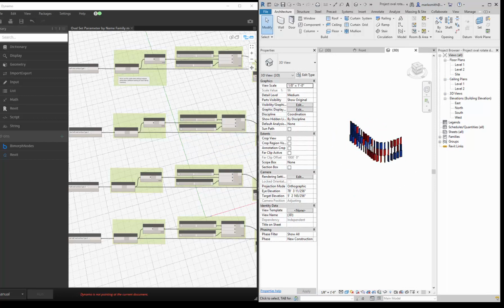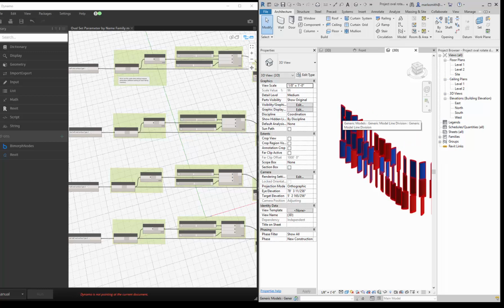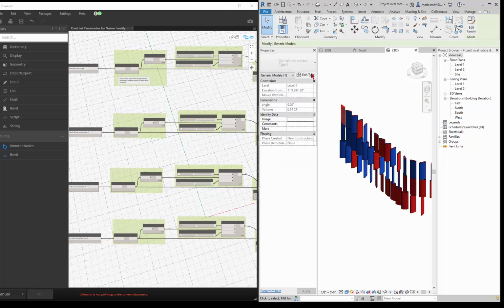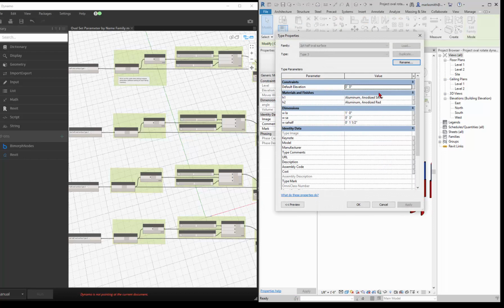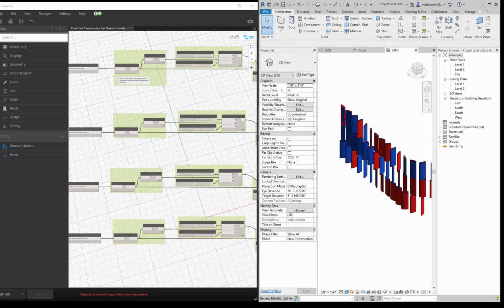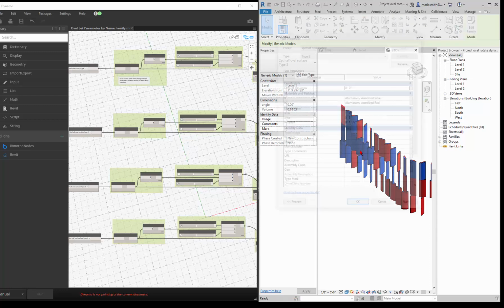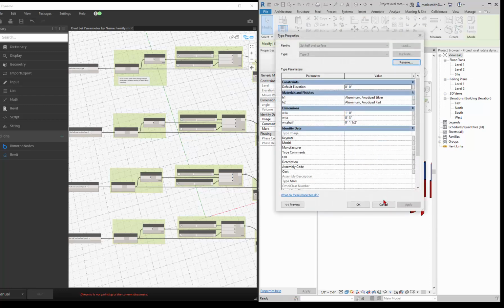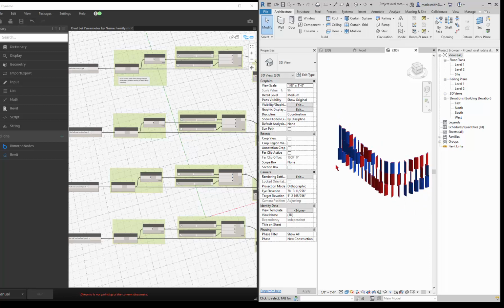Okay, so that's what I've got for now. Go ahead and give it a shot, setting it up, maybe one of your lines, and see if you can get it in there and get it to work. Maybe the final thing is how to change the material: you can tab select into these guys even in the project and edit type, and you'll see the material on each side. You can change them, and anything you run into later we can talk about.